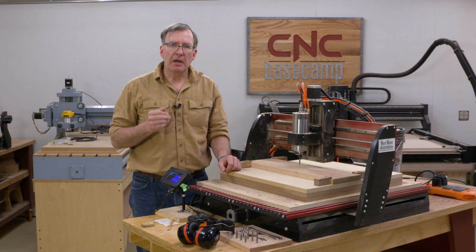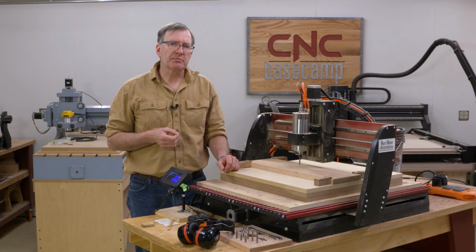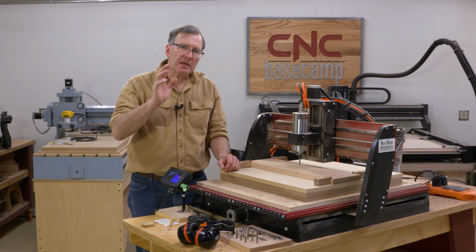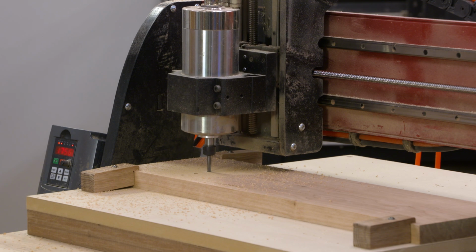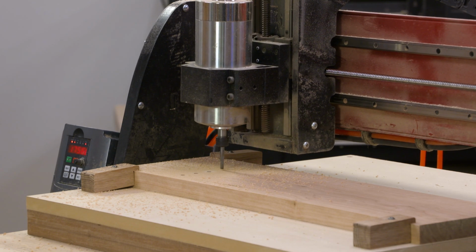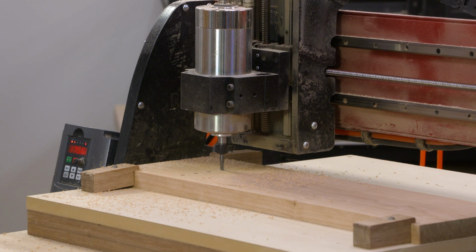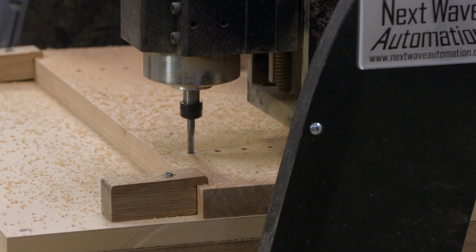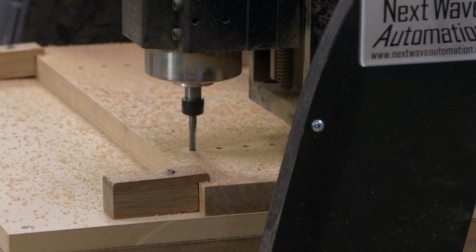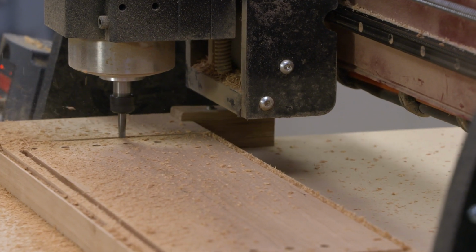You know, dowels are an underused form of joinery because, well, they're always a little bit tricky to get things perfectly lined up. But with our CNC machine, it's not a problem. The CNC is going to cut perfect holes in the top and the bottom, and I'm going to use it to create a simple jig which will allow me to drill mating holes in the ends of the sides. The machine's going to begin with drilling the holes for the dowels, then it's going to proceed to cut a slot for the back and the final profile cut.